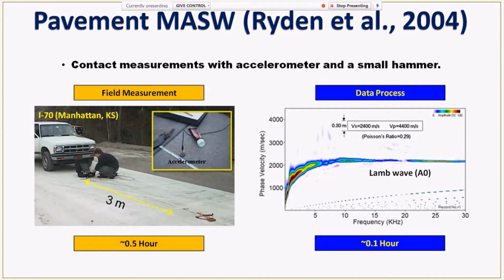But in comparison to a normal MASW survey, which deals with tens of meters depth and also horizontal distance of at least 100 meters or sometimes up to tens of kilometers, the dimension that he was dealing with at that time was a very, very small scale, almost a microscopic scale, because depth range was almost a few tens of centimeters. And also the horizontal distance that he was dealing with by using either a shot array or a receive array was only a few meters.